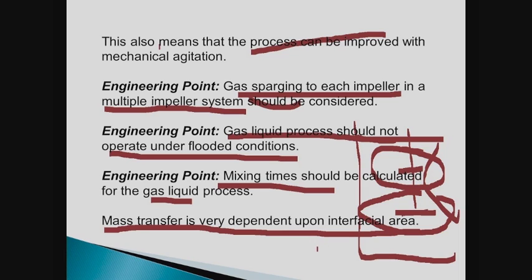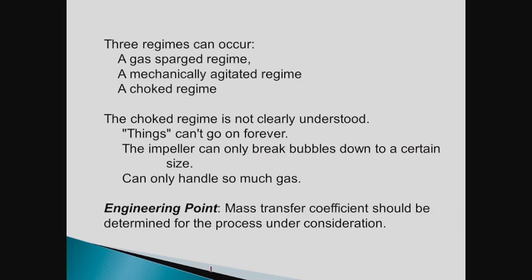You have this sponge, and the bubbles in the sponge are very similar to the bubbles in your tank. Down here, you always would like to have still an impeller on the tank bottom, not necessarily a gas dispersing impeller, but a small impeller just to keep a dead zone from happening down there.